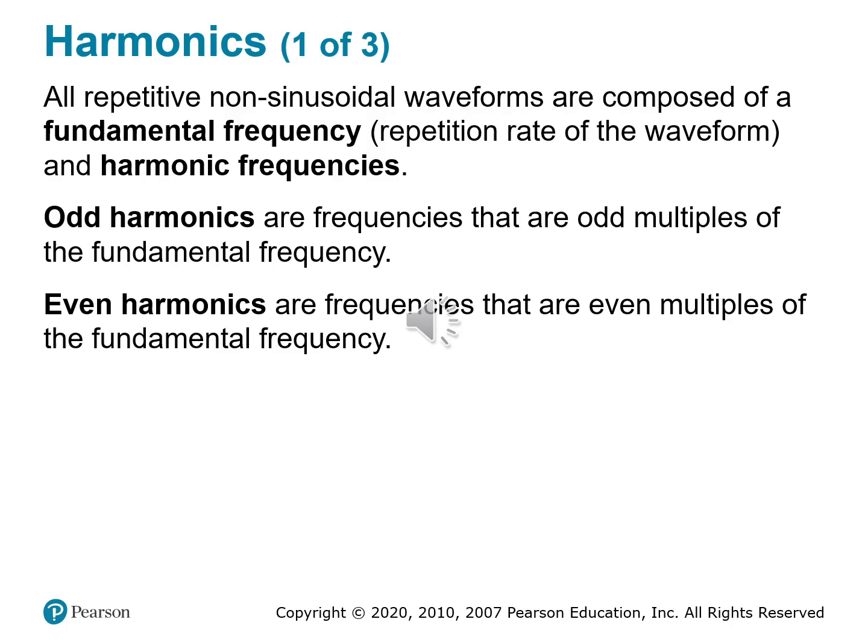So when we say a waveform is non-sinusoidal, what we really mean is that it's made up of a fundamental sine wave plus a bunch of harmonics riding on top. And the presence of these harmonics determines the shape of the waveform, the sound quality if it's audio, and the frequency content in filtering and signal processing.